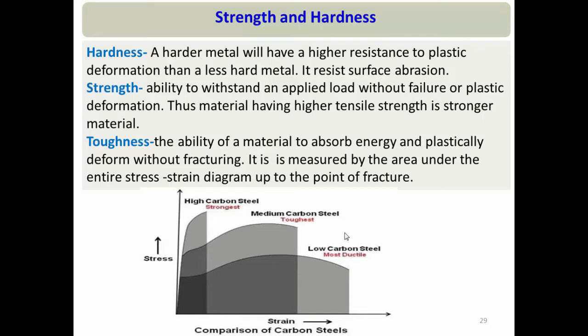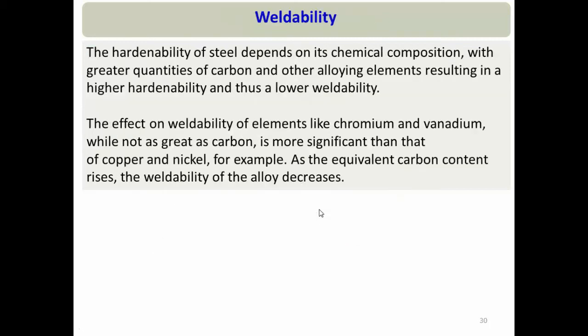When we discuss different types of material which we use in refinery, we will talk about all these parameters in detail. But what we find is, when carbon decreases, material weldability also increases. So there are two important parameters of a material: hardenability and weldability. Now, hardenability and hardness are not synonyms. Hardenability is not related with the highest hardness a material can obtain. Rather, it is related with the depth or thickness over which a material can obtain its hardness.